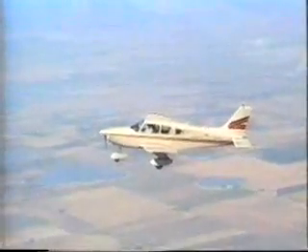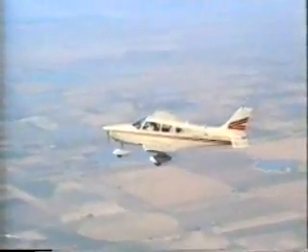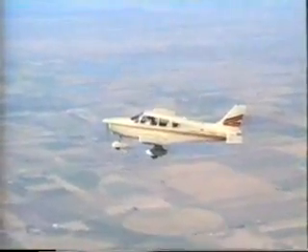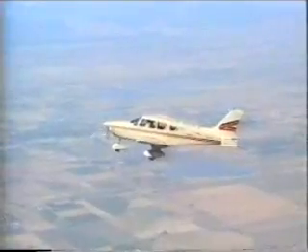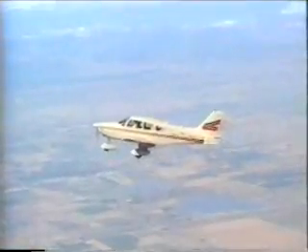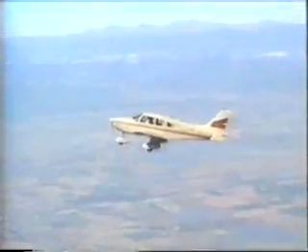While the relationship between angle of attack and airspeed is fairly constant in level flight at a given weight, significant changes occur when the flight conditions vary. Aircraft weight, maneuvers, and configuration alter this relationship. At a given airspeed, a heavier airplane requires a greater coefficient of lift to maintain altitude. This increase in lift is supplied by either a higher velocity or an increase in angle of attack.